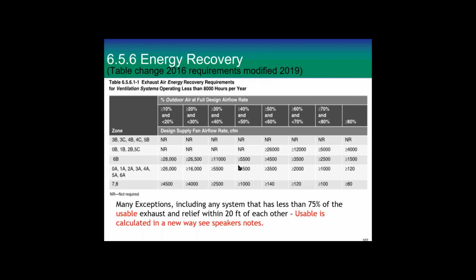So there are many exceptions, and the biggest one is that if you've got your exhaust fans all over the roof or all over the building, and it'd be very expensive to duct them together to get them back to the unit, then you don't have to do anything.